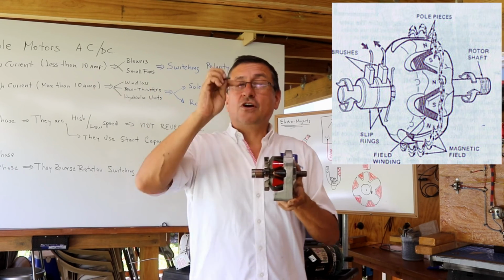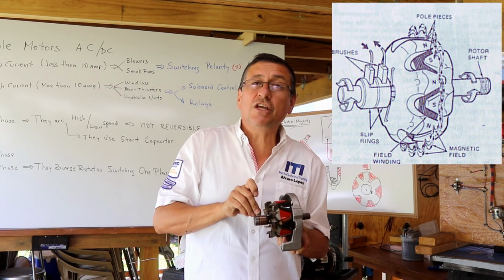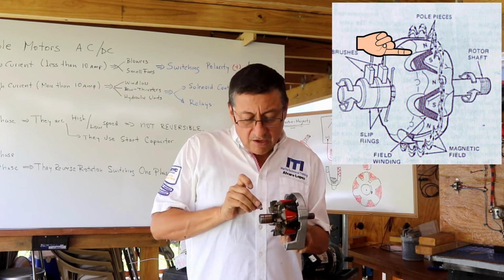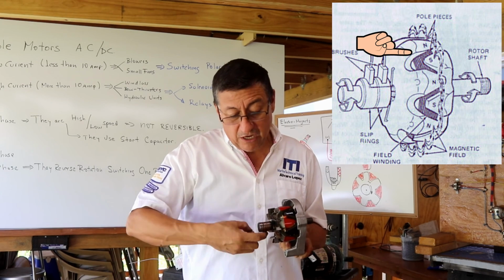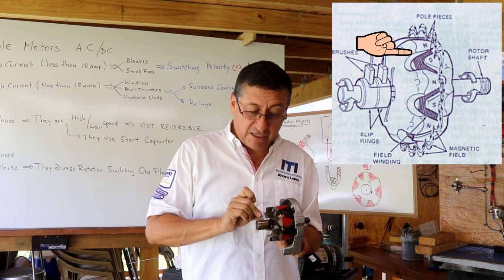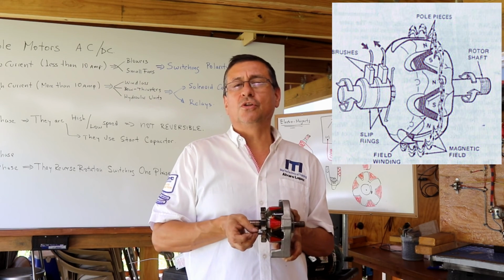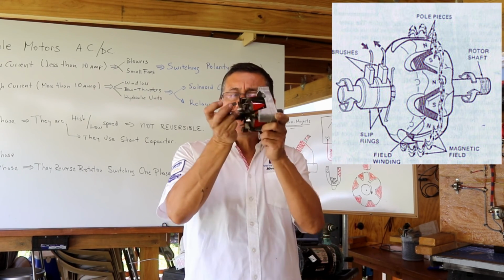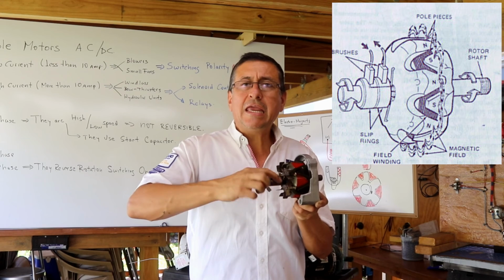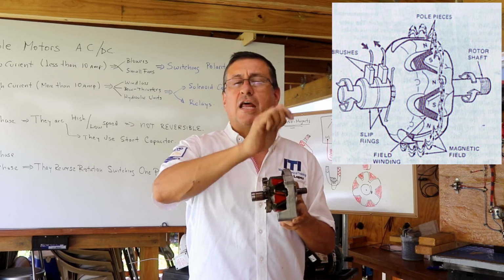The life of the production of electricity in the alternator depends on the quality of the excitation. If the excitation is good from the battery, from the ignition switch, the power produced is strong. If the excitation is not good because the slip rings are contaminated with oil or dirty in between the brush and the slip rings, the excitation is poor, and the output power is not good. For that reason, you need to periodically send the alternator to the machine shop in order to replace the brushes and clean the slip rings, to produce better excitation and, of course, excellent output power.